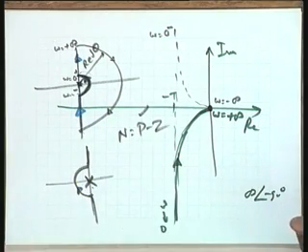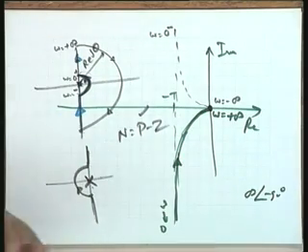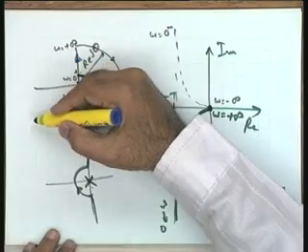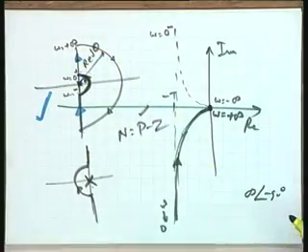This is an open loop pole, and we are interested in the stability of the closed loop system, please. So will N encirclement be different in this case? Yes, in the two cases N will be different. For the same system, the answer on stability will be the same, but the N obtained in the two cases will be different. Okay, so for our discussion I always take this particular picture.